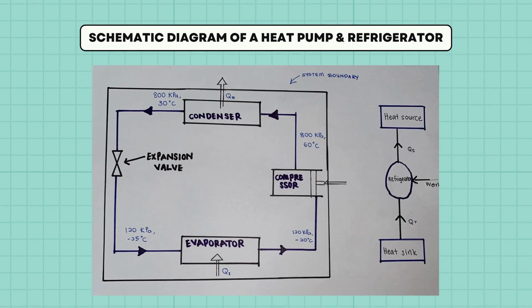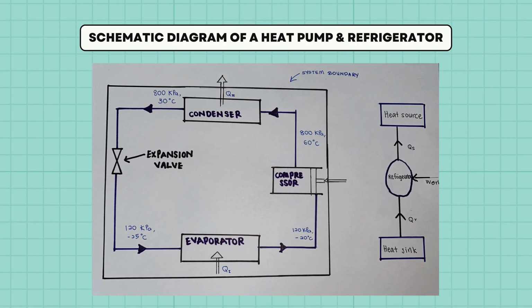Let's compare the refrigerator to a heat pump. Both systems use similar components and principles to transfer heat. Here, you can see the compressor, condenser coils, expansion valve, and evaporator coils in both devices. The refrigerant absorbs heat from one area and releases it in another. In winter, it can extract heat from the outside air and release it inside, while in summer, it can do the opposite.